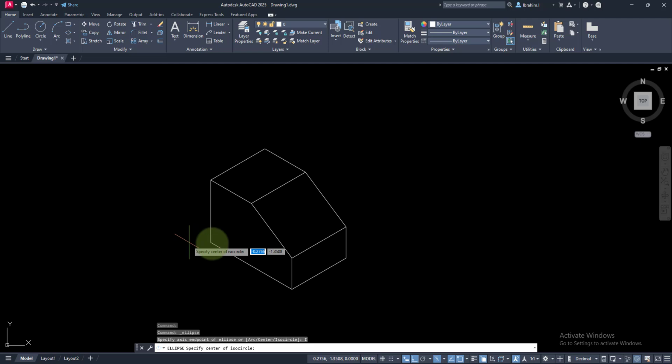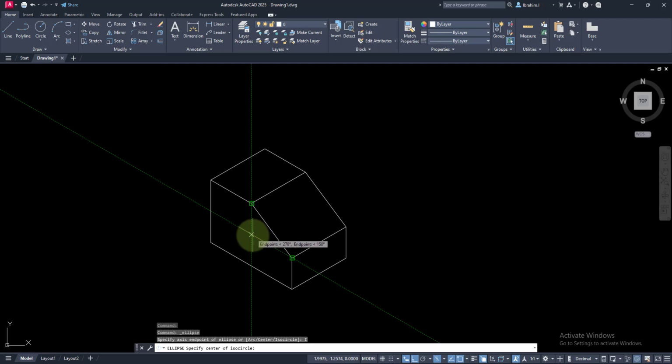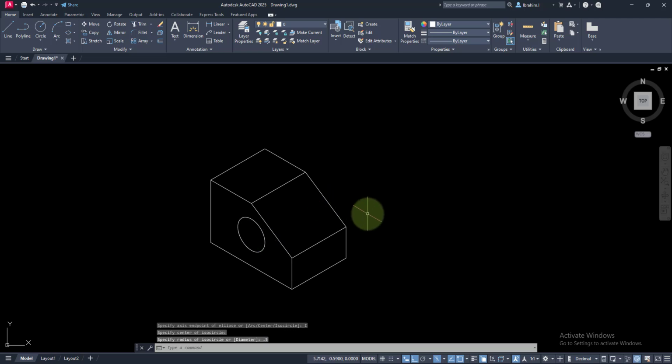Anyone works. So I'll go ahead to track from here using my object snap one more time, and I'll go back here and then look at it. When I click and create, can you see, tada, this is exactly what we are looking for, right? Remember what the radius is again. I'll go to 0.5 because 0.5 is what we have. Then I'll click, and you can see that we have that circle correctly placed. Are you guys with me?